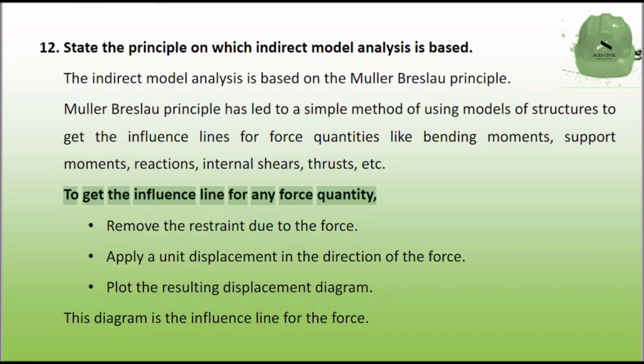To get the influence line for any force quantity, remove the restraint due to the force. Apply a displacement in the direction of the force. Plot the resulting displacement diagram. This diagram is the influence line for the force.